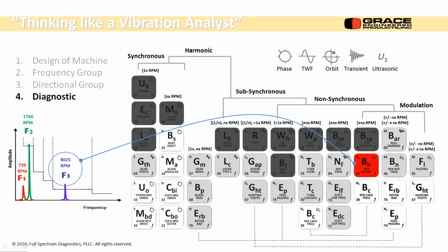Okay. These three will have three specific frequencies that we'll be looking for. If we know the bearing make, model, and type vendor, we can determine what all these frequencies are. So two of them didn't pan out. This is the one that fits the mold. So it had a bearing defect and it had a mechanical looseness type A problem. So looseness in that bearing was likely what starts the jackhammer effect, and it shows up on the bearing as the bearing starts to fail. Okay.